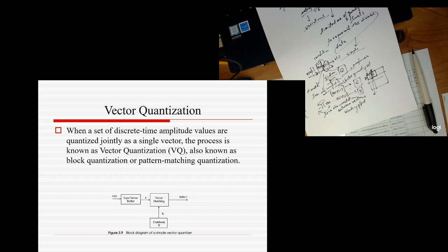Scalar quantizer performance is worse; the vector quantizer can do a better job because it considers more data correlation. However, it also has a blocking effect between vectors. A scalar quantizer treats samples independently, so it loses the correlation between samples.